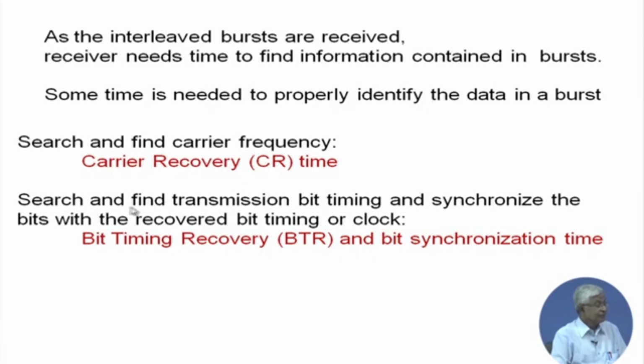So you have to search and find the bit timing, and synchronize your local bit clock with the recovered clock. This is called bit timing recovery. To recover the bit timing you need some extra time to synchronize. So it is called BTR.